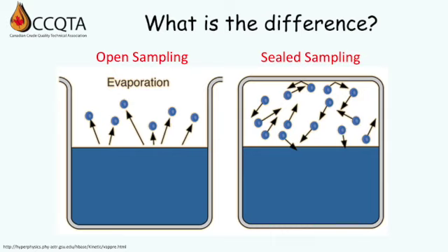In a scenario where there is negligible C1 through C6, the vapor pressure will be very low. Therefore, evaporation will be slow and loss will be more limited. In the opposite scenario, where C1 through C6 are prevalent or even dominant, the vapor pressure will be much higher and the evaporation loss will be much quicker.